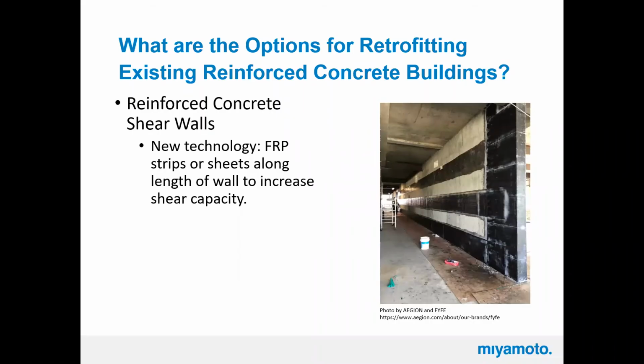And here's another method too, adding shear strength with FRP. It looks like there are also some boundary improvements at the end of the wall. You can see the vertical FRP at the ends of the walls, and then the horizontal strips of shear reinforcing that's been added to this wall to strengthen it. Like I said, this is pretty easy to install too.